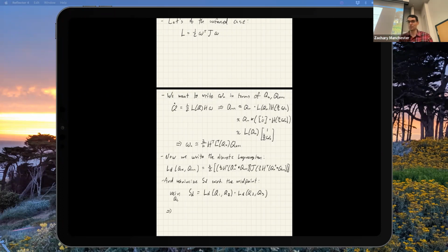And again, this is stupid simple. I literally am just taking the derivative with respect to Q2 and then slapping on that attitude Jacobian to impedance match us back to 3D derivatives. So that looks like this. I'm taking the derivative with respect to Q2 of this guy, and then I multiply by the attitude Jacobian evaluated at Q2. And then I do the derivative with respect to Q2 of this guy, and I slap on the attitude Jacobian here with respect to Q2 again.